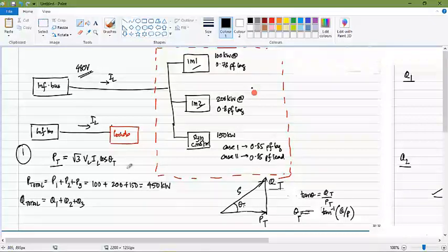What about this theta t, the total theta? That represents the overall power factor of our power system. We can't just do an algebraic summation of all three. That will be suicidal. There is a way that we can find the total theta of the system. We are going to use the power triangle that we all know from our applied electricity AC fundamentals.